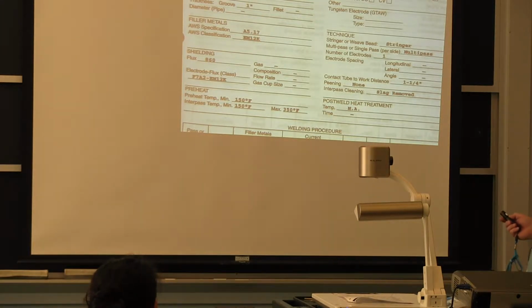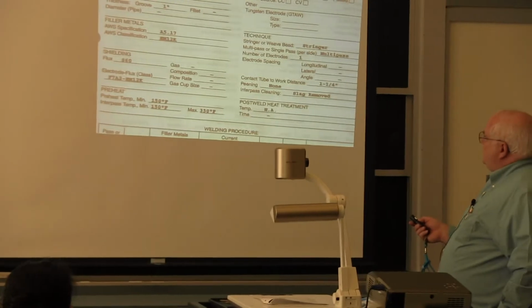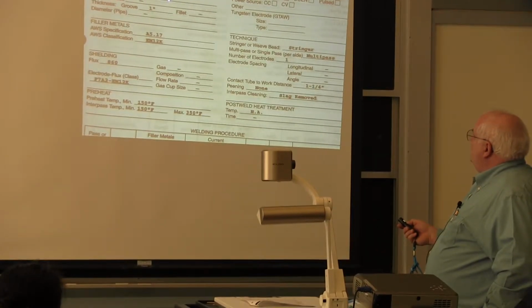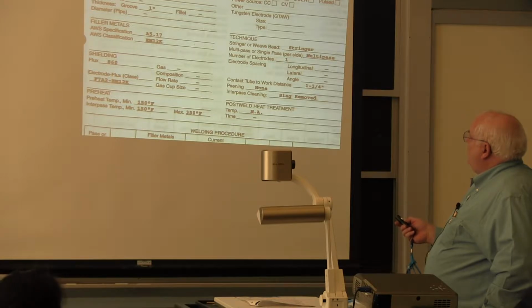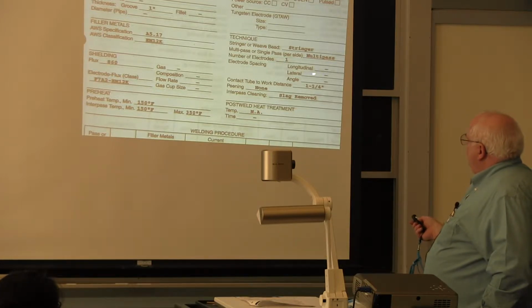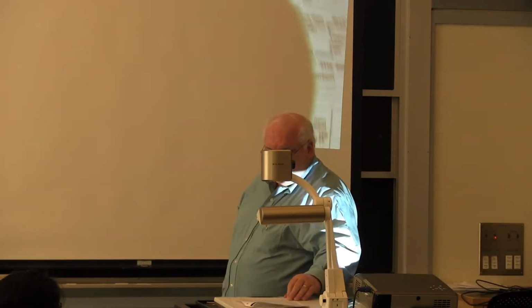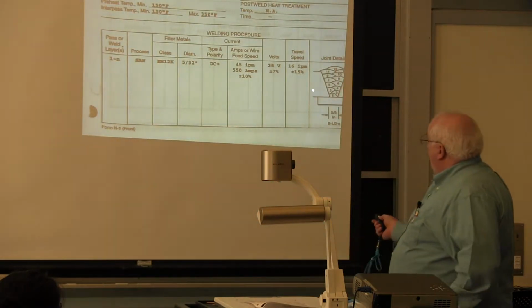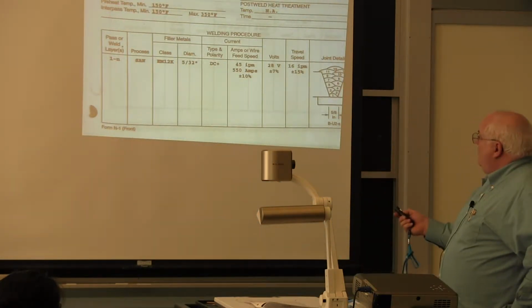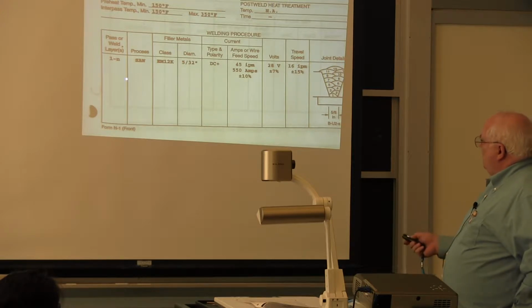So here's an actual one that's filled out. ASTM A36, garden variety carbon steel plate, and it will qualify. It tells you the geometry of the weld and the stringer. They don't have to fill in everything. Sometimes you just put a blank there, which means it's not required. The code tells you in excruciating detail what needs to be filled in and what doesn't, okay?